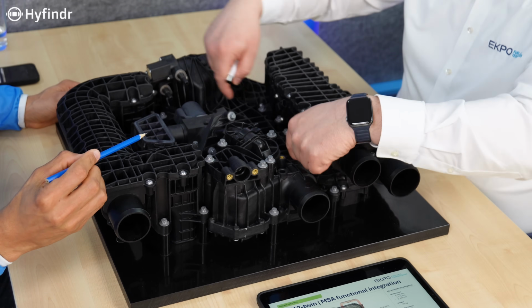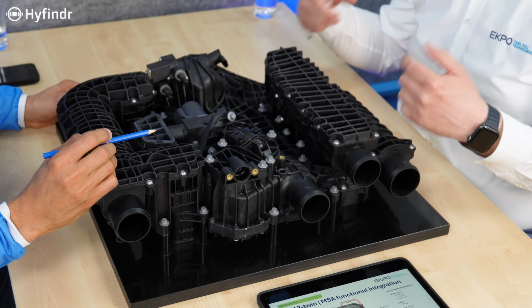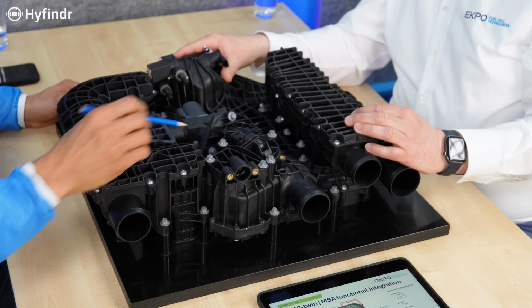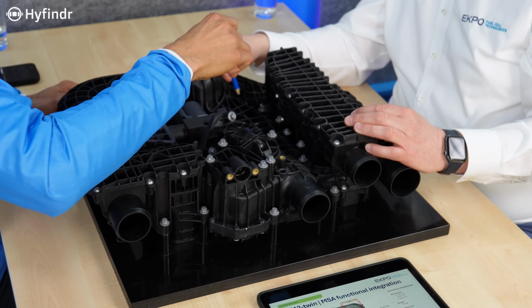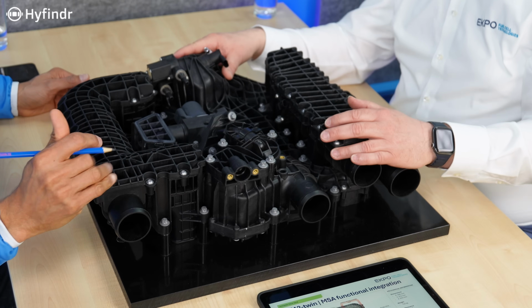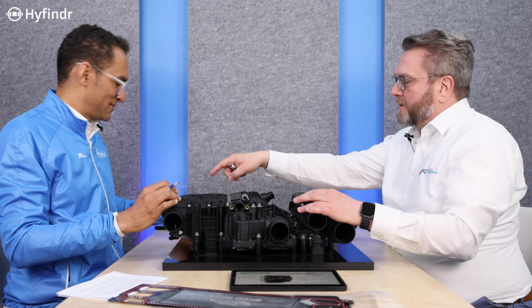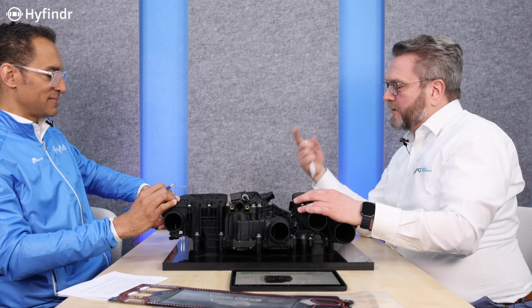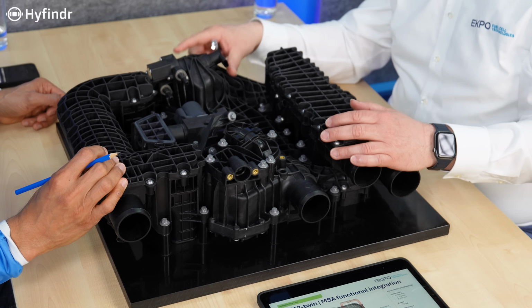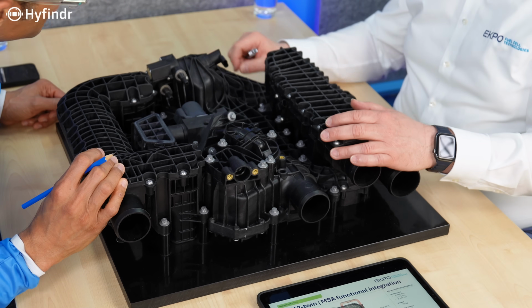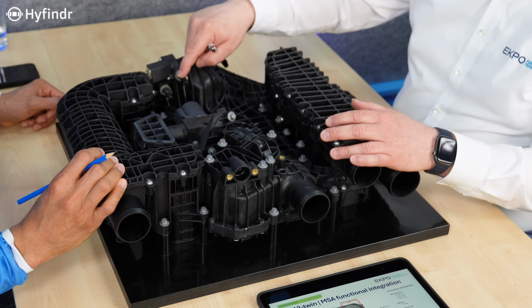If hydrogen comes back from the stack, because some of the hydrogen is not consumed, because we want to have hydrogen flow, it's then brought into the droplet separator. It's coming back here, these two lines, going into the droplet separator. Because the hydrogen then has to exit to the recirculation pump, and this is a high velocity pump, so it doesn't like liquid water. So we have to remove it here. There's a level sensor where we control the filling of this water separator. As soon as this is filled, we drain the water from here.